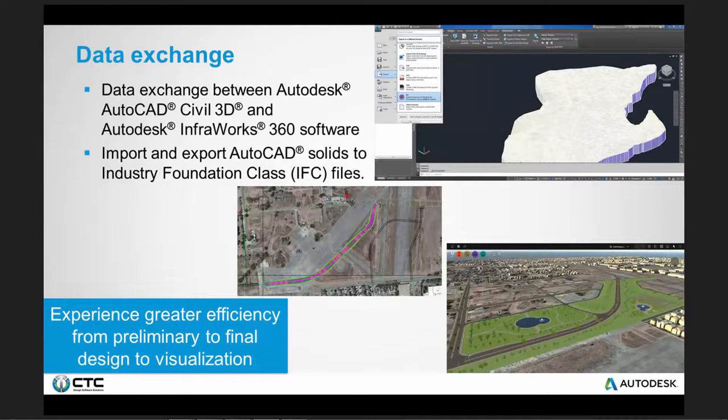This is very powerful in that we can have it scan that InfraWorks model and convert design roads or surfaces or water features into direct Civil 3D entities, be they polylines or native alignments, profiles, surfaces, parcels, and so forth. So some really nice data exchange there as well.